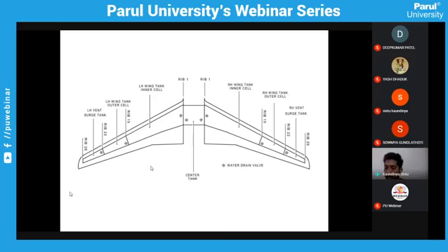Okay, but this can only happen when the difference between the fuel tanks is only a few liters, a few hundred, mostly at max 1,000 liters. If there is a much higher difference, you have to dump the fuel in air. I think you guys have heard of fuel dumping, right? They just open the valve of the fuel and the fuel falls down like water in the air. It doesn't fall on the ground because fuel is very volatile and it will evaporate before it touches the ground. Okay? Is it clear?